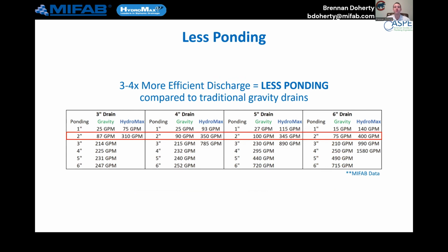Most importantly, though, we have a more efficient drain, creating a safer overall roof. Not only do we have reduced maintenance costs for the lifetime of that building, not having to worry about the clogging leaves, we have a drain that's going to pull that water off the roof at a much quicker pace, which means I have less standing water. So that 30-year roof, maybe the owner is getting 40 years out of.